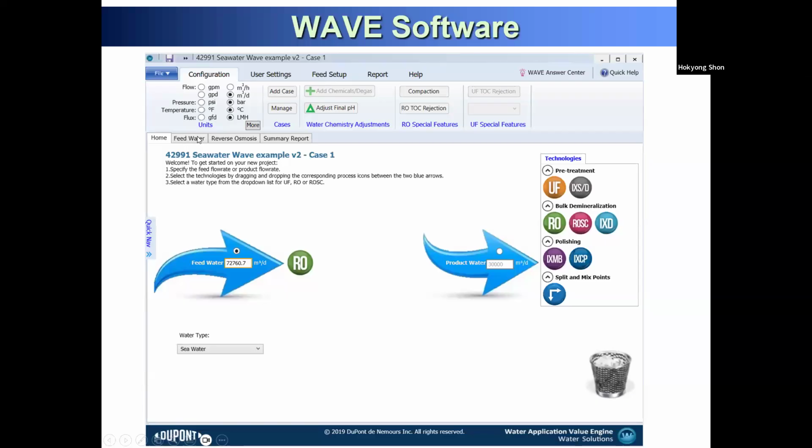And this is the feed water side, reverse osmosis membrane design. So you can put how many elements, which membrane type you want to select, what the feed flow rate, concentrate flow rate, average water flux is, also how many elements you need. So everything you need to put into the reverse osmosis, what we have studied last session. And then you put your technology inside.